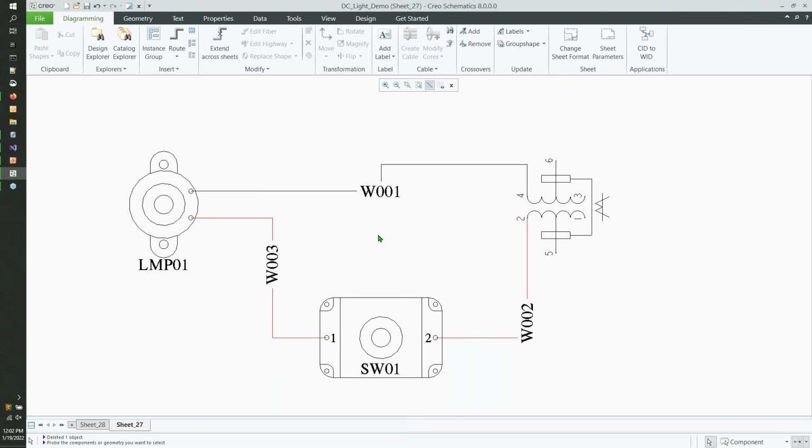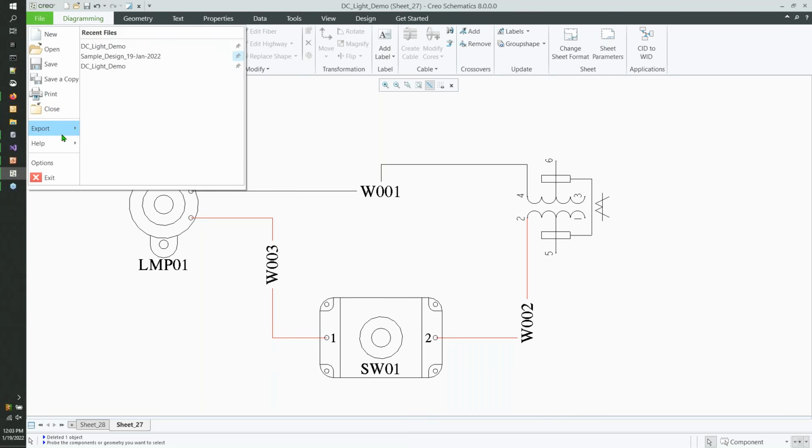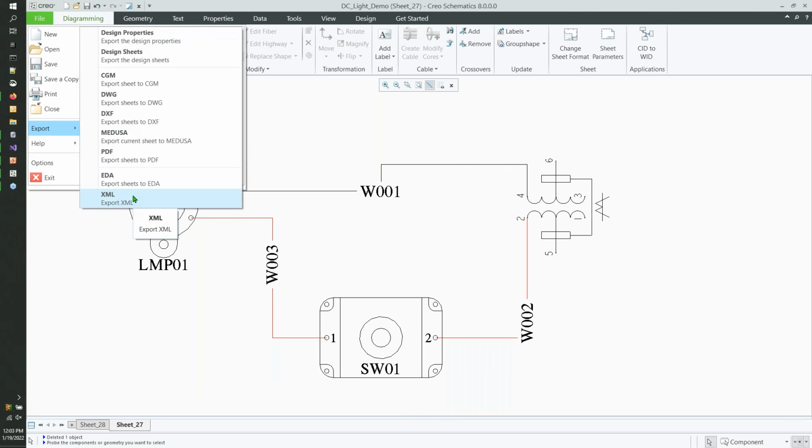To look into that and just to kind of briefly speak to that theory before we transition into a question and answer format, let's take a look at what that would look like, and we'll open up Creo Parametric very quickly. While it's not our focus in schematics today, let's take a look at what we can get that's maybe more tangible than historically the flat paper sheet theory that we're looking at right now. With that being said, we would go about this process by exporting our XML, which is the export format that PTC is utilizing between schematics and Creo cabling.